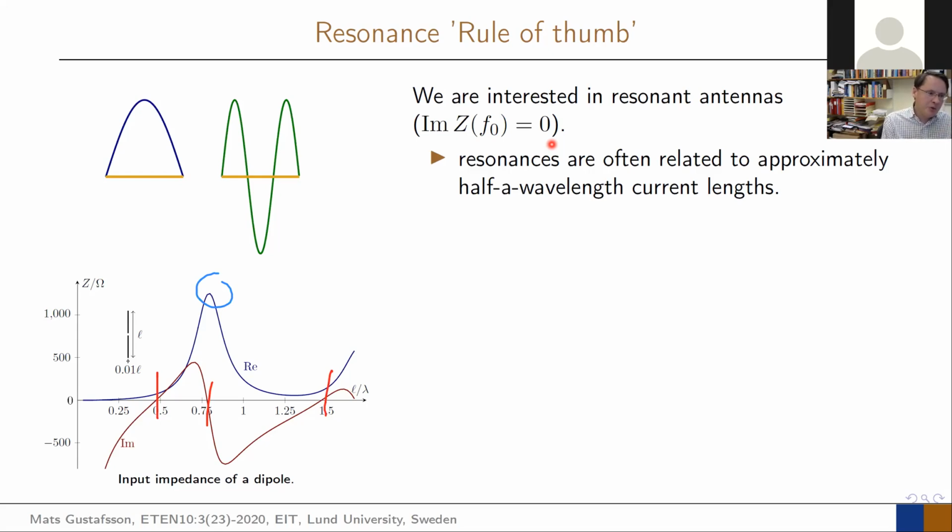And for a dipole type antenna, it really means that the current is very low in the feed, which means that in typical cases you cannot use it. But when you come to your patch antenna, it will typically actually sit in this case. It will be similar to that one. So it's not always bad. And then you have the first resonance where you actually would like to be in most cases. And that is the one here that is slightly below. So that's the one there with the pattern that looks like that.